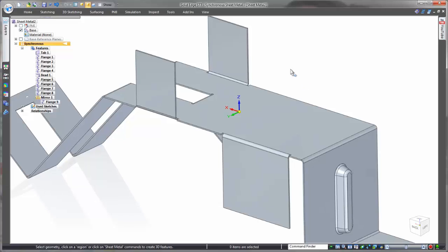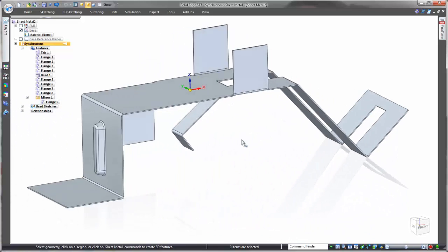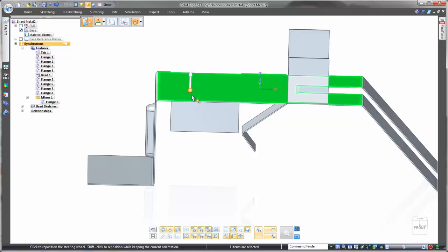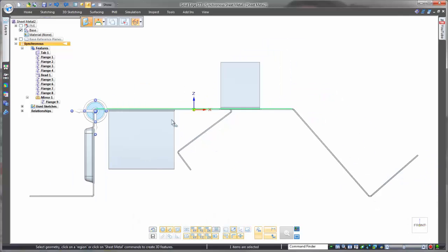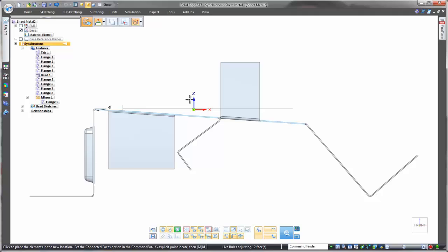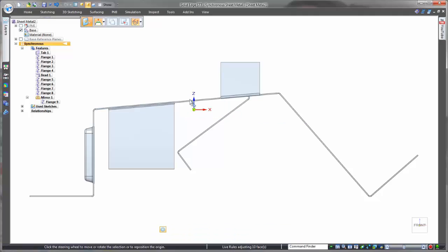When we created the very first sketch, we locked that sketch to the top reference plane. At this point, I've changed my mind and decided the top face needs to be at a 5-degree angle. In most other history-based CAD systems, this change would be a no-no because of fragile feature dependency. Not with Solid Edge. Pick the face, move the steering wheel, and rotate. Wow, that was easy.